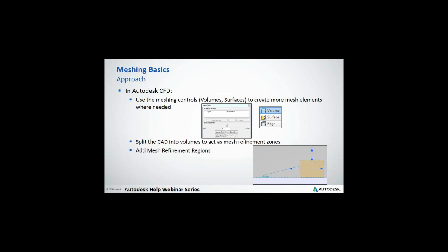Hey, Amal, just a few notes here. Splitting the CAD is great when you still want an automatic mesh, which means it's not uniform, but you in general need to enhance and tighten up the mesh. So this is used all the time on airfoils, and there are old webinars of people doing airfoils. They'll have 3, 4, 5 CAD volumes around the airfoil.